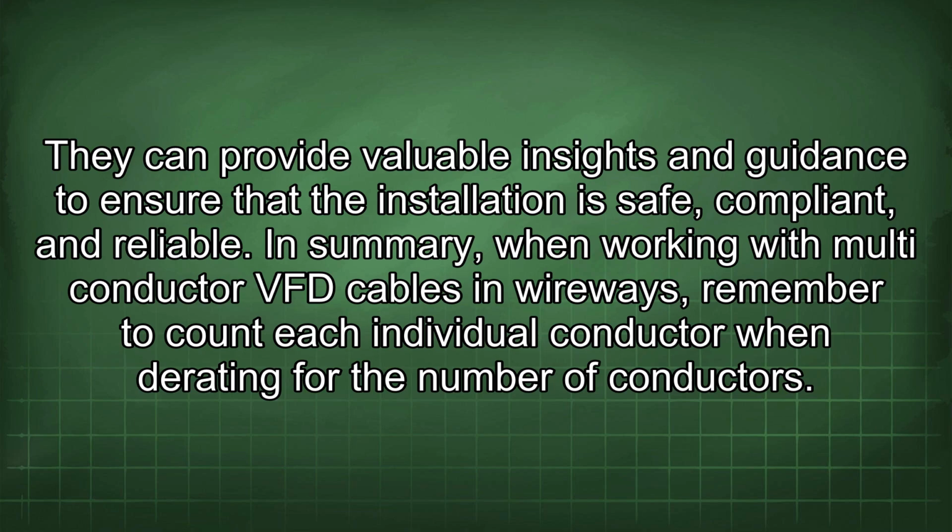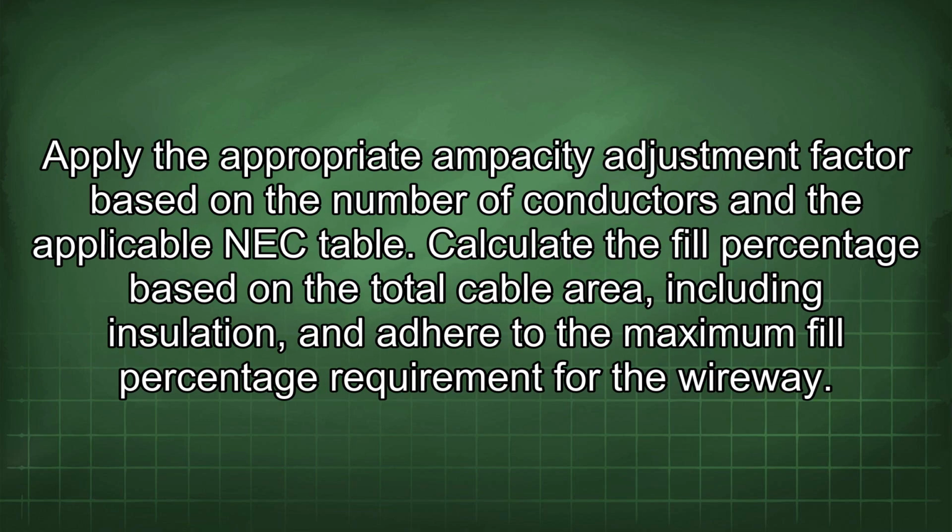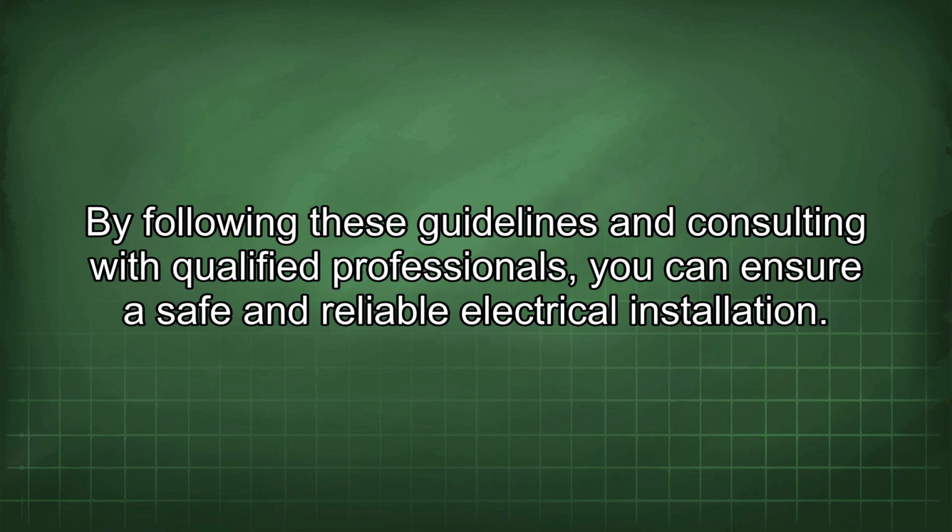In summary, when working with multi-conductor VFD cables and wireways, remember to count each individual conductor when derating for the number of conductors. Apply the appropriate ampacity adjustment factor based on the number of conductors and the applicable NEC table. Calculate the fill percentage based on the total cable area, including insulation, and adhere to the maximum fill percentage requirement for the wireway. By following these guidelines and consulting with qualified professionals, you can ensure a safe and reliable electrical installation.